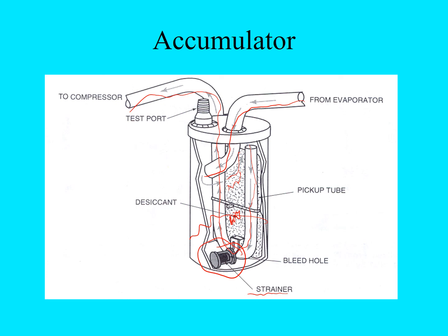So a little bit of refrigeration oil would move through this accumulator, and refrigeration oil might collect in the bottom. So as the refrigerant moves through, any oil is going to be picked up by the refrigerant and actually goes on to the compressor to lubricate the compressor. But an accumulator is used with the orifice tube system.